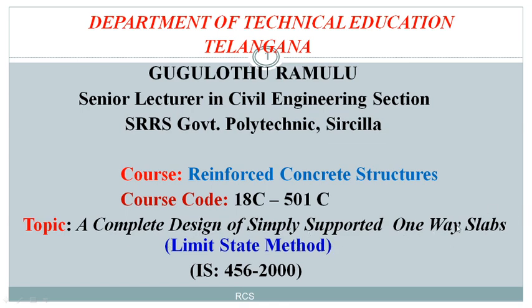You know what we mean by a one-way slab? A one-way slab is one where Ly by Lx is greater than 2, then we can design it as a one-way slab. Here, Ly is the longer span of the slab, and Lx is the shorter span of the slab. If the ratio of these two, Ly by Lx, is greater than 2, then we can design it as a one-way slab.